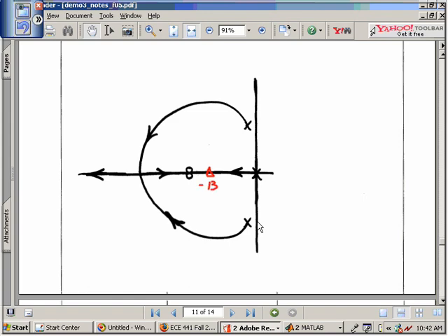The idea is that that will be a large enough gain so that these poles, which are moving from their -2.5 to plus and minus j17.5, are actually getting inside this 45-degree wedge.